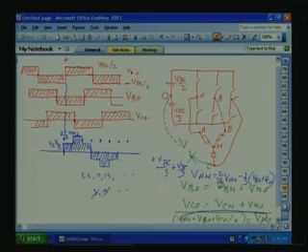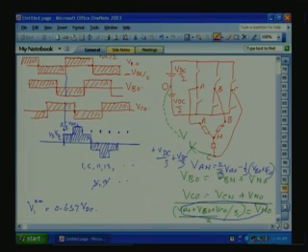So, if you do the Fourier series of this one, the peak fundamental V1 maximum will be 0.637 VDC. This you can do the Fourier series and you can find out. So, for this waveform, the maximum V1 maximum will be 0.637 VDC.